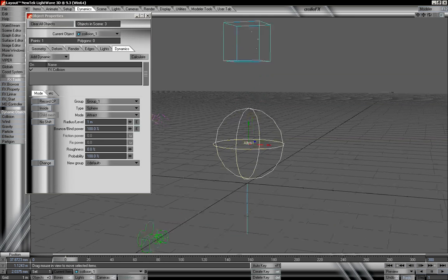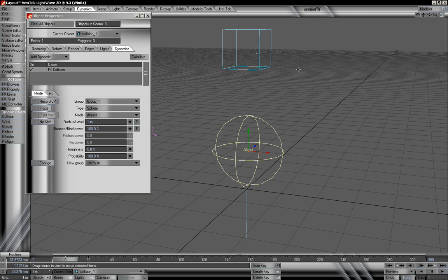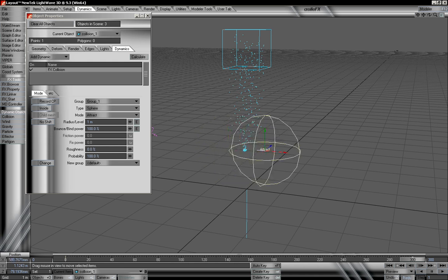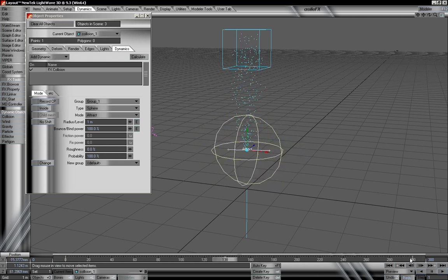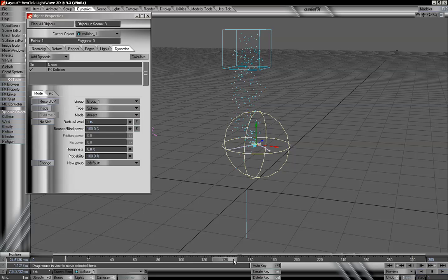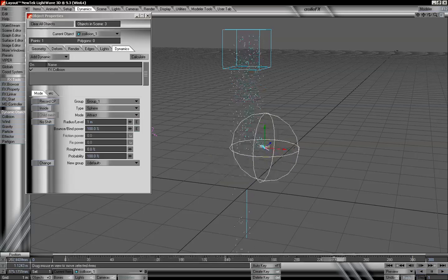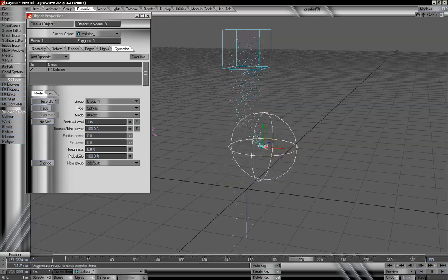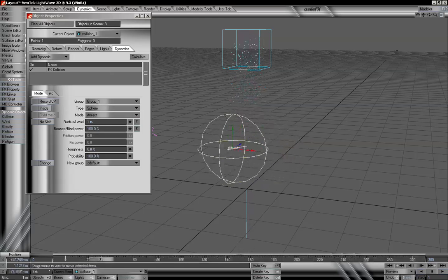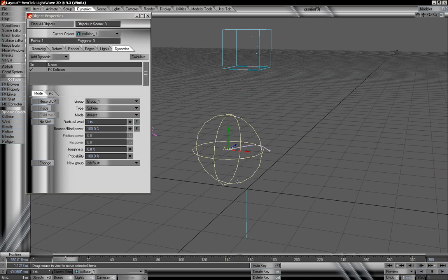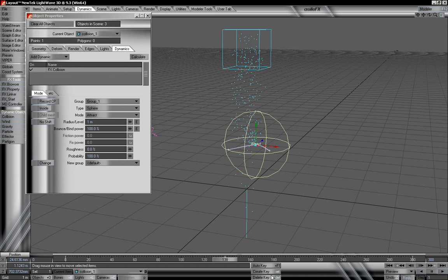And of course we can animate this as well to create a really neat looking effect. I'll just create a quick animation. Drag to frame 300, move that over, and inside we can move that a bit, and now we can see as the particles enter, as it's moving, they will all be attracted to the center, and the particles that are not within the collision will of course continue to flow down and not be affected. We'll go to our different keyframes and delete those for this collision.